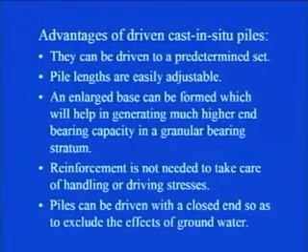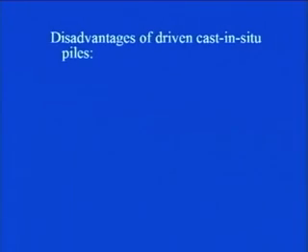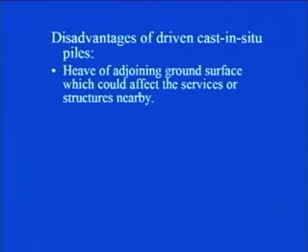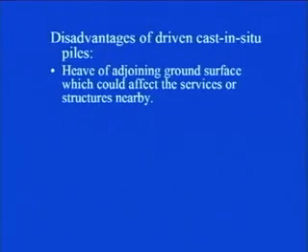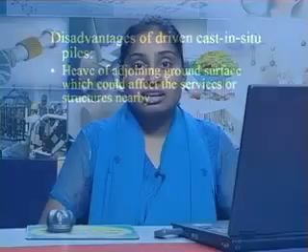Some of the disadvantages of driven cast in situ piles: heave of adjoining ground surface, which could affect the services of structures nearby. Let us say a very sophisticated structure is there in a nearby location, which you have to protect from any kind of vibration. In that case, while driving the pile there will be a lot of vibration and heave also can occur. So, that is one of the disadvantages of driven cast in situ piles.